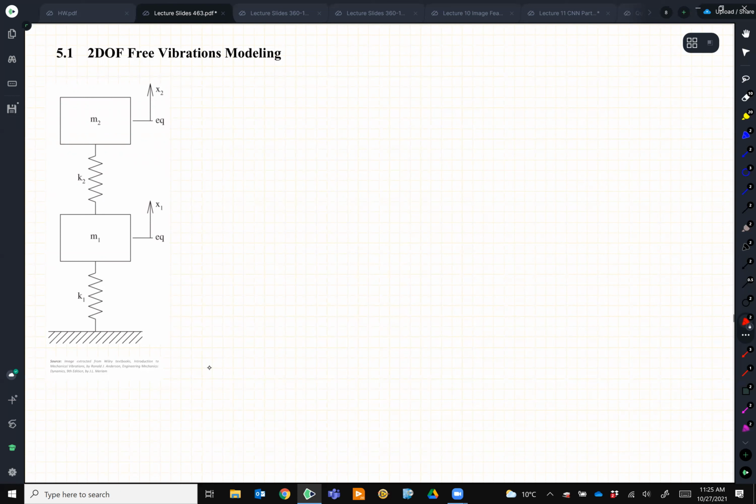Then we attempt to solve them, and we try to find what this system will do if we just excite it naturally. We'll find its natural frequency. Then we add damping to the system. Then we add external excitation. We will do the same steps here, but for n degree of freedom system. Okay, let's do that. So I'm going to derive the equation of motion. This is what we mean by modeling. We have 2 methods. Let's start with our friend Newton.